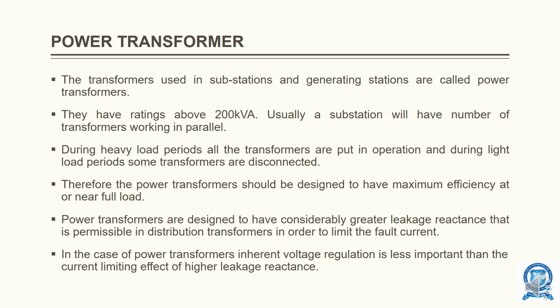Therefore, power transformers should be designed to have maximum efficiency at near full load. Power transformers are designed to have considerably greater leakage reactance than is permissible in distribution transformers in order to limit the fault current. In the case of a power transformer, inherent voltage regulation is less important than the current limiting effect of higher leakage reactance.